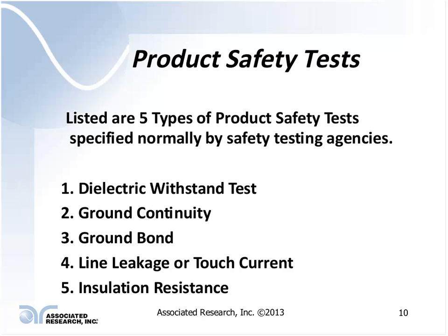A ground bond test is typically specified to be conducted for a 2-minute period, and it's done at twice the fuse rating of the product or at a particular current level, which typically may be the higher of the two, and it varies depending upon the standard itself. But we'll talk a little bit about that also as we go into the particular test itself.